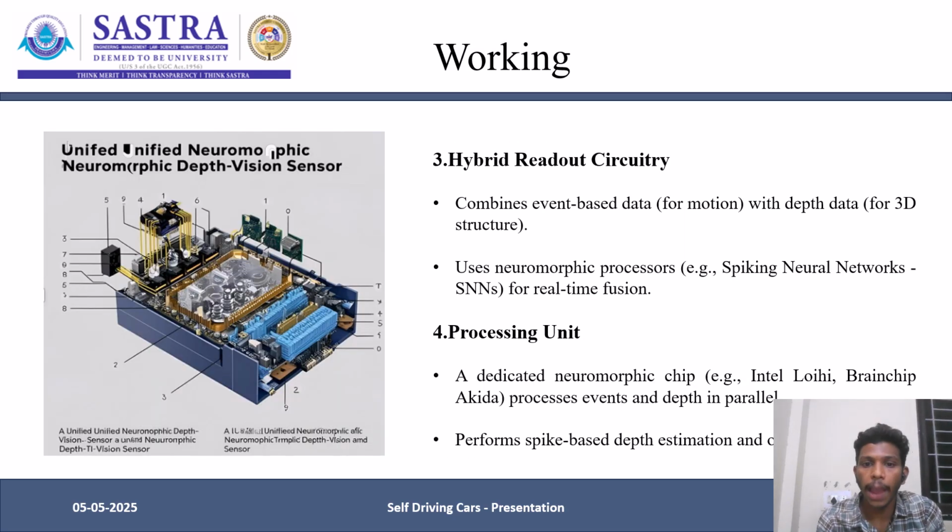And the hybrid circuitry combines the event-based data and the depth data and uses a neuromorphic processor for real-time fusion. For the processing unit they have used Intel Loihi or BrainChip processors for the events and the depth in a parallel manner. They perform spike-based depth estimation.